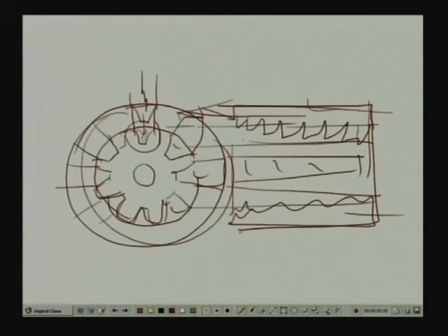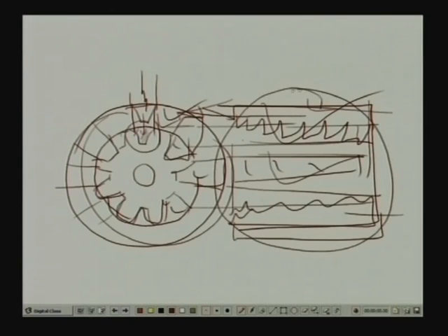Again, this is a good part, that you get very high productivity in one stroke. You get a gear, you can produce internal teeth also by a rod-like cutter, and dimensional accuracy and surface finish will be good. But remember, if the number of teeth changes, then the entire broach has to be changed. If the module changes, then another broach has to be used. The broach as such is very complex, very costly, maybe 20,000 to maybe up to 1 lakh. If you change the number of teeth or module or helix angle or pressure angle, any feature of the gear, a separate broach has to be procured.